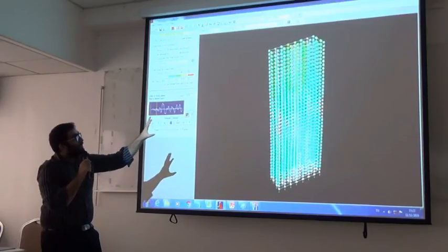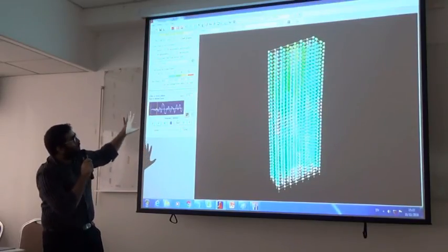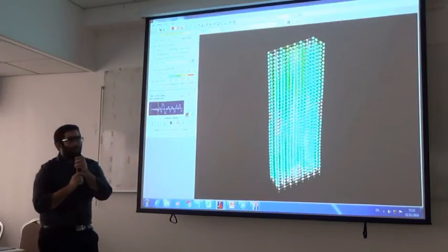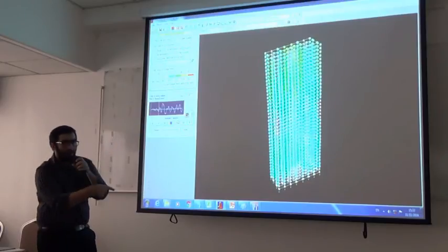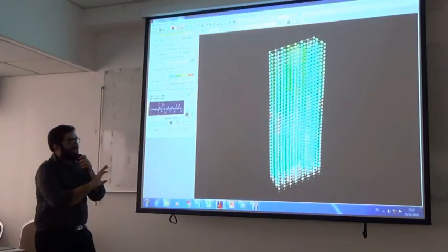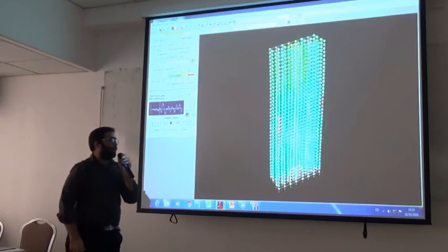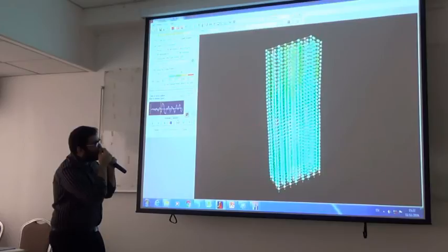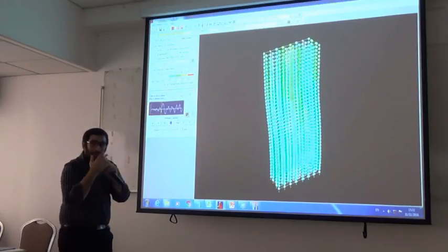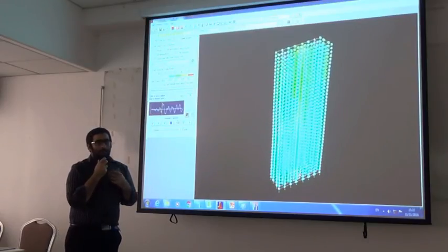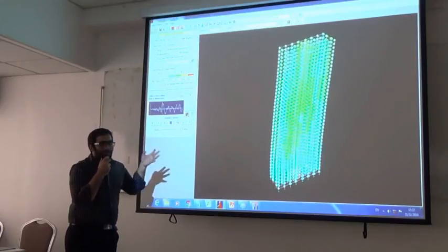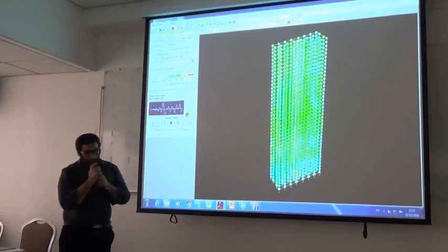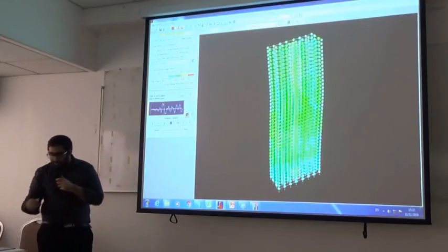The green color that you see in the building is for the DC ratio of 0.2. So if your rotation capacity is 0.025, you multiply that by 0.2, you get the green color. So you can know that the number is exceeding that rotation. But you will not see any red color over here. Basically meaning that the rotation that I already defined in the deformation capacities is not being exceeded, because the red color will correspond to a DC ratio greater than 1.